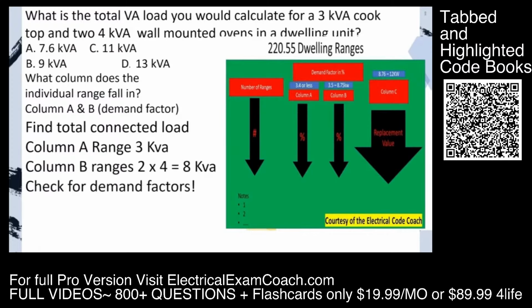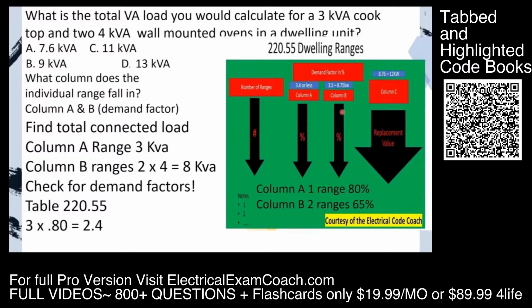Now, we check for demand factors. We head back to our table, and we start on the left-hand side for our column A ranges, and we find the multiplier for 1, and then we start on the left-hand side and find our number of ranges for our column B ranges and find the multiplier, and we're going to find that they're 80 and 65% respectively. Now, all we have to do is do the math. We take our column A ranges and do the math, take our column B ranges and do the math, but then we can't forget to total them back together, and we're going to select A.